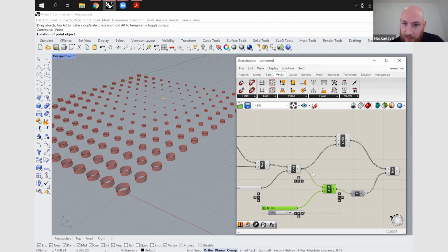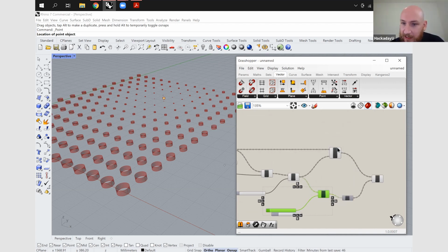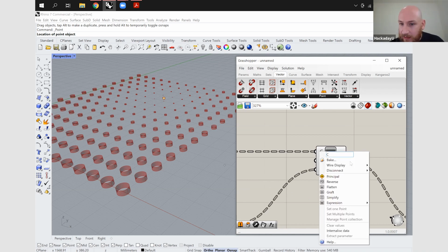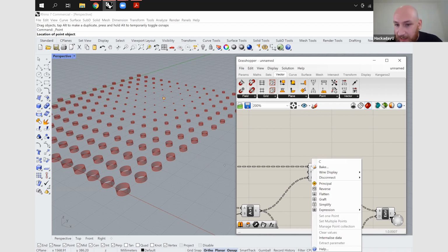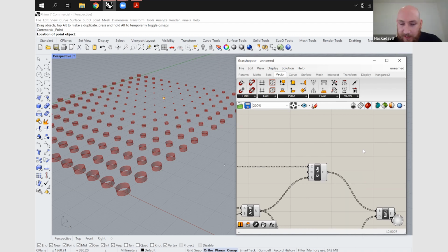How do you delete connections between nodes? So just right click where the connection is. And on this one, fourth down is disconnect. And if you have multiple things connected, you hold shift down if you want. If you connect something, it replaces it. But if you hold shift down and then you release the left point, that would add multiple points. So if you right click on them, disconnect, and it will give you a list of all connections, and you can just disconnect them there. Hope that answers your question, Brent.